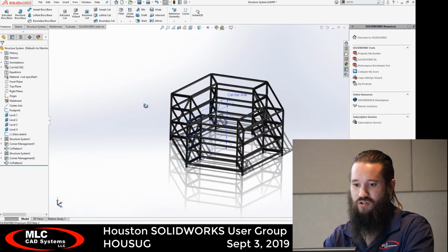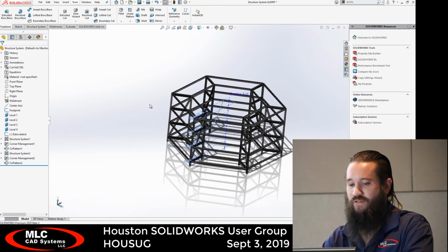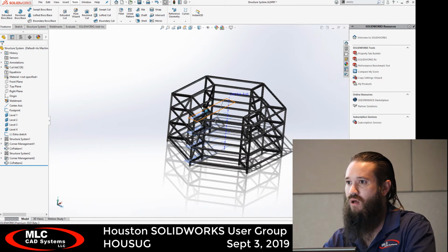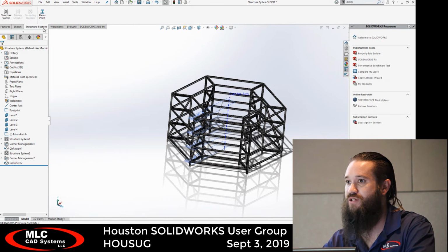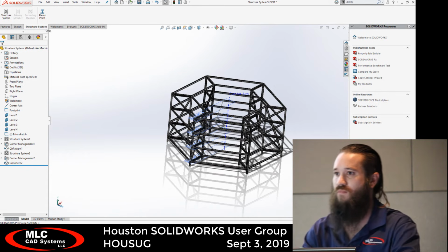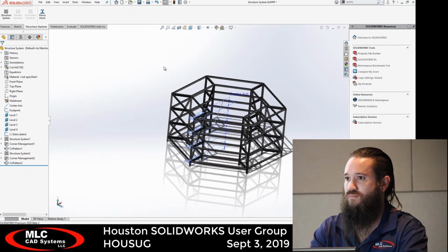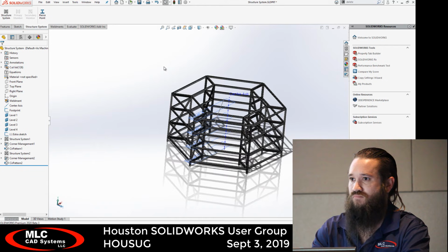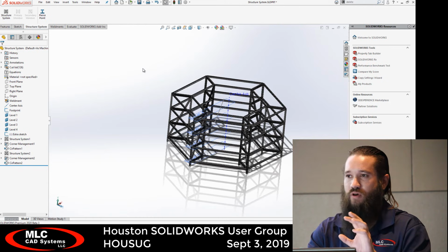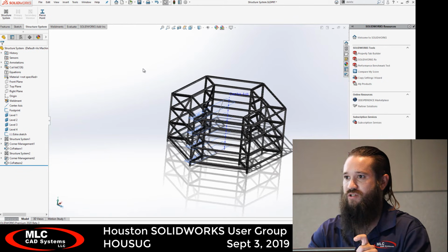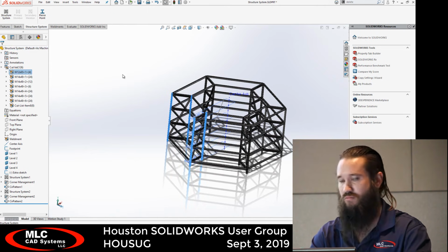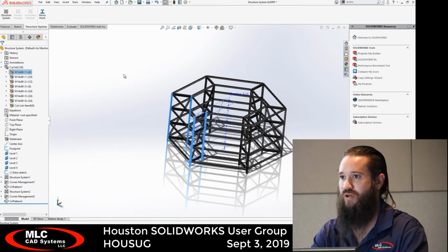Add something that's not a structural shape. To find out which one is better to use, like performance-wise? Oh, are you talking about for like end cap creation and stuff? Yeah, you could just do a normal extrude. Right. And there's no difference in the way that we deal with plates between Weldments or structure systems. It's just a boss extrude, and then you would define the thickness and whatever material you've got from your cut list here via right click.